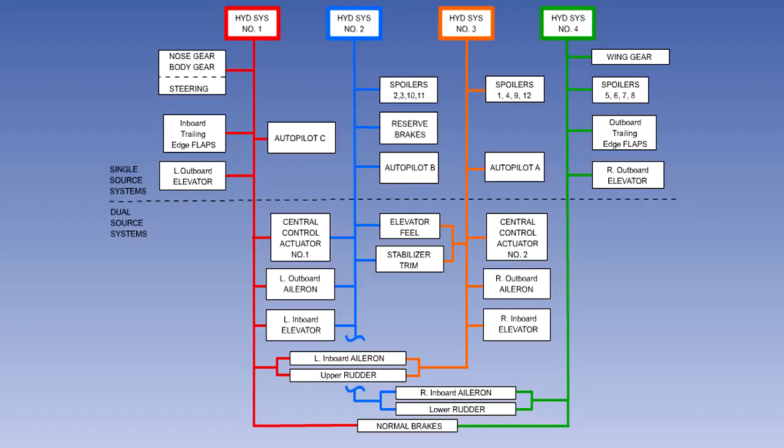Most modern aircraft will have multiple hydraulic supplies available for flight controls. 2, 3 or even 4 independent hydraulic systems can simultaneously supply power for the primary flying controls. On the Boeing 747, for instance, each primary flying control is split into 2 separate parts, and each part is fed by 2 hydraulic systems, so a pressure-maintaining valve is not required.